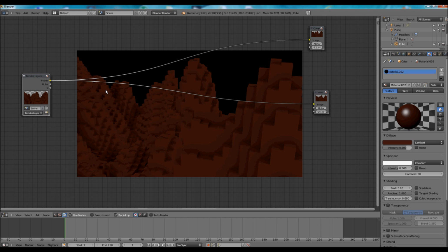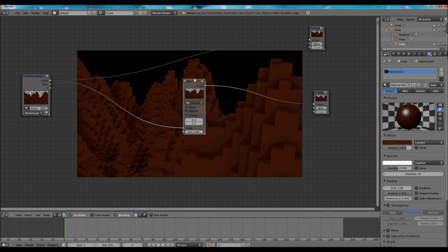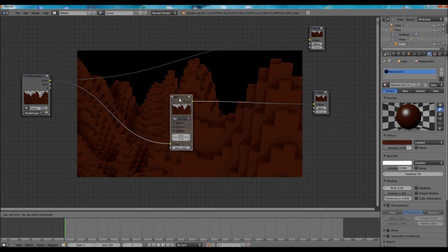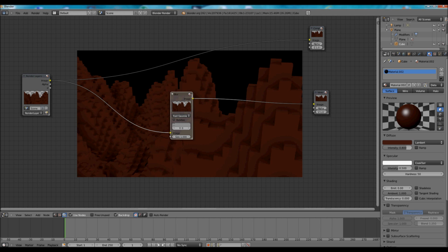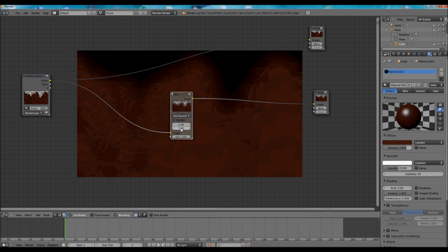I was using a blur filter in order to get this glowing effect. So press Shift A, from filter choose blur, and you can manually connect the dots, or you can move the node over a line, and then the dots will be connected automatically. And I think first of all, I used something like fast Gaussian, and then, if I remember correctly, 80 or something like that.